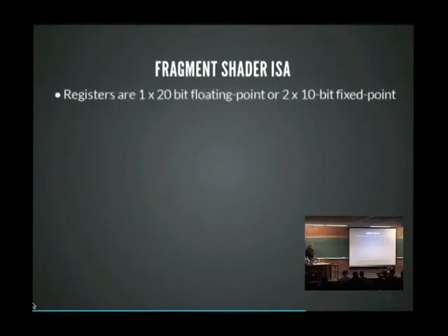Yeah, the fragment shader ISA is quite a bit more interesting and crazy. All the registers are either representing one 20-bit floating point value or two 10-bit fixed point values. That's 2.8 fixed point signed.